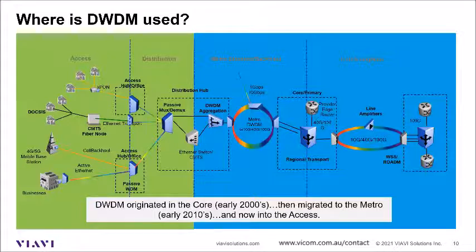So I want to discuss a little bit more what we mean by access. Here, for instance, we see a 4G, 5G mobile base station. And here we have a color code. So that means that this distribution hub has this multiplexer. So it's feeding different wavelengths into this access hub here. And then from this component, which is a demultiplexer, it can separate a wavelength that will feed the mobile base station, but it will allow the other wavelengths to get into a business, or maybe it could be a single wavelength, could be multiple. So over here we can have other streams depending on what we want to feed. So all of these components at the end of the day are running on the same single fiber back into the distribution hub.